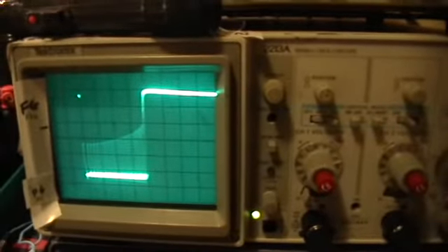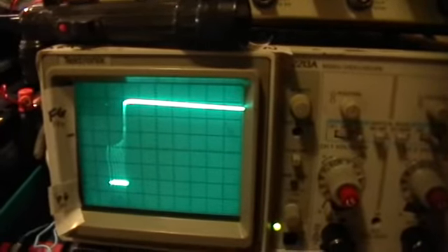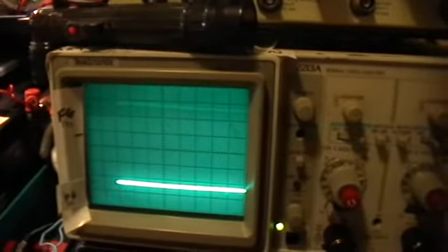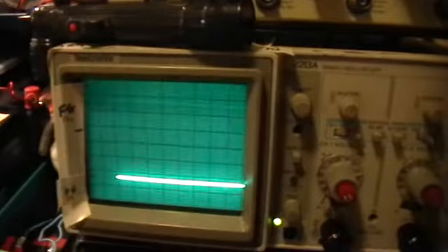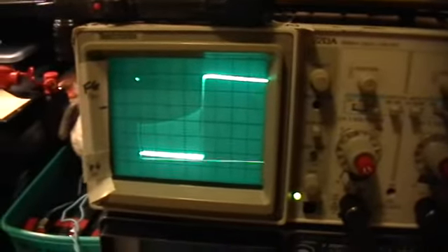And so what you're seeing right there is just the output of the 555 timer. It's a very dirty signal. I'm going to vary the duty cycle now, and you can see how that gets shorter and shorter and shorter to the actual cutoff edge of the pulse, and then finally the scope loses its trigger and it goes away. Now the MOSFET is doing its best to amplify what you're telling it. Okay, so if you're feeding it a dirty signal from a 555 timer, that's what the MOSFET's amplifying.